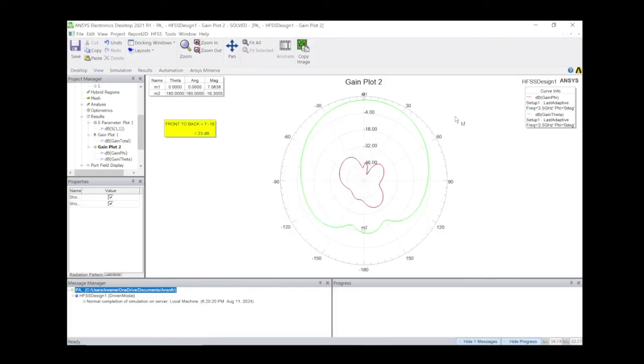the half power beamwidth. So we will add other markers. We move to this direction, and when you are moving towards that direction, we should check what's the M1, the magnitude. So it should be 3 dB less of the magnitude. So when we have 4, then we stop. We have 6. You should be checking this side. We have 6 point something. So 5. We have 4. So we can leave the marker here, and we start from this point. It should also be 3 dB less than the magnitude that we have.